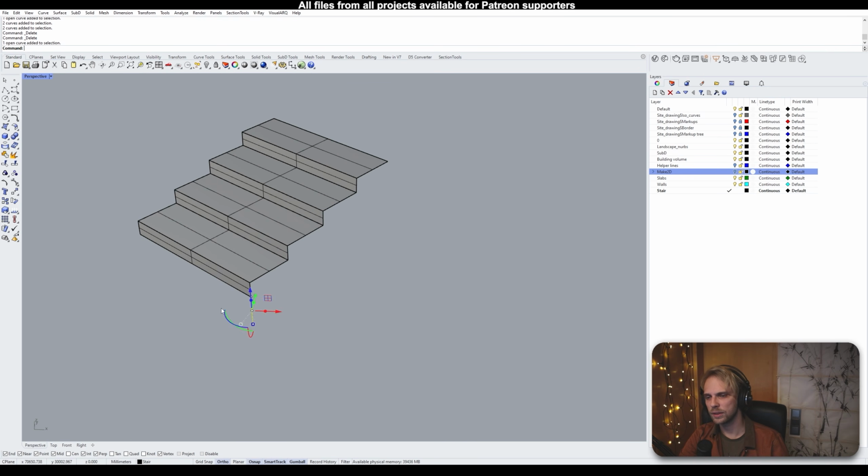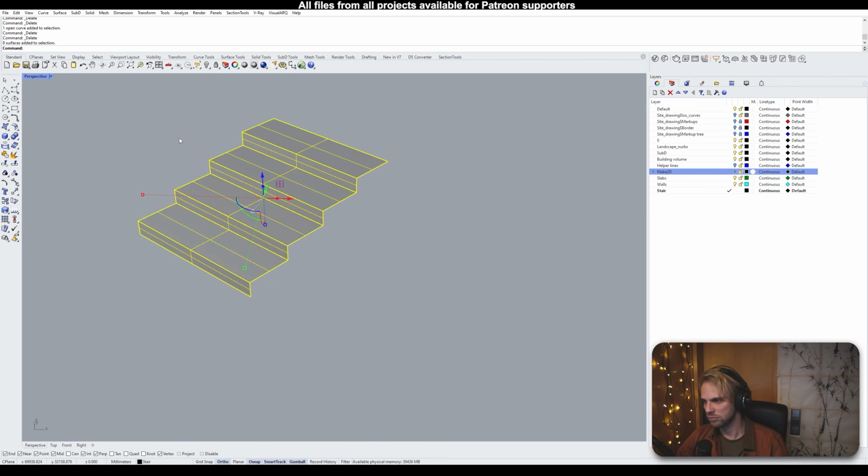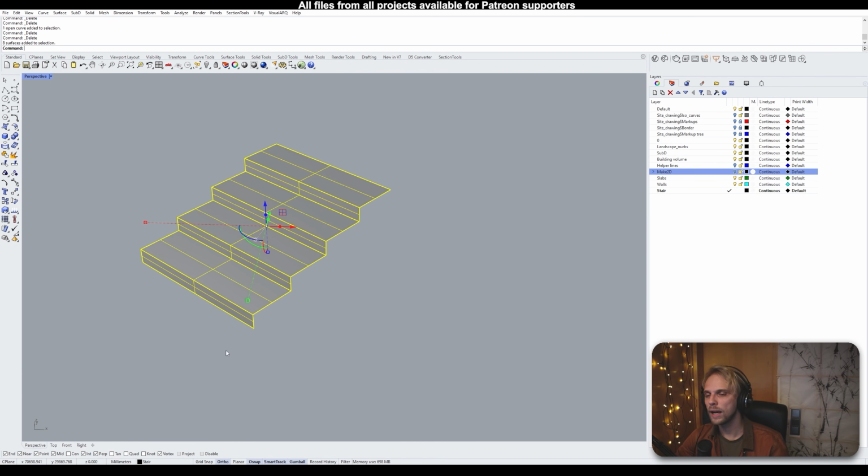I will not be doing this just to save time, because this is not going to be the method that we will be using particularly for the staircase that I'm going to be showing to you. But why did we choose 0.1 meters or 100 millimeters in step size? That makes no sense. Well, because the way you control the height is not at the start of the stair creation, but in the middle.